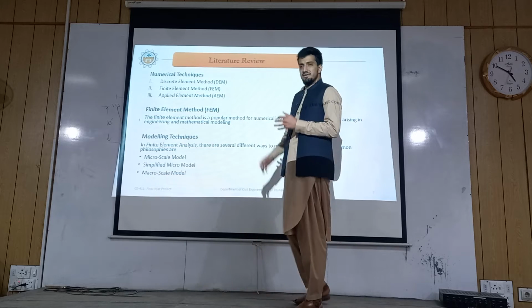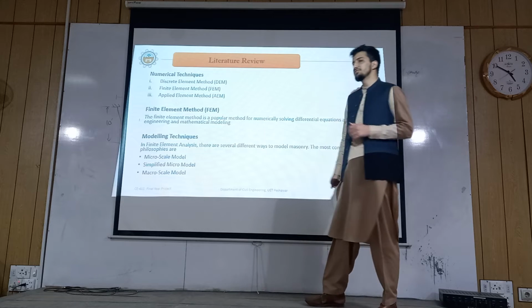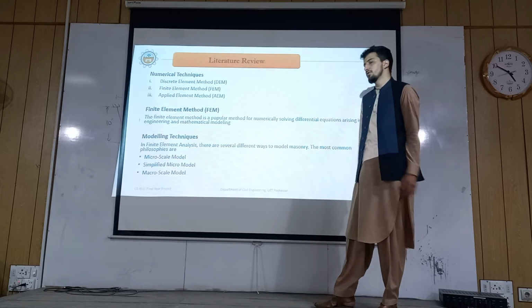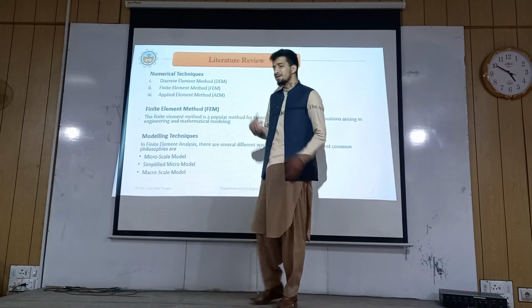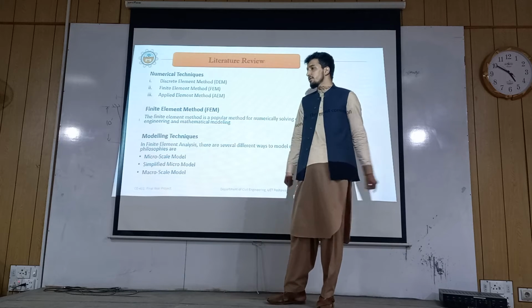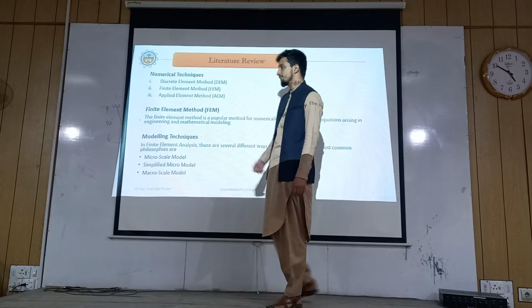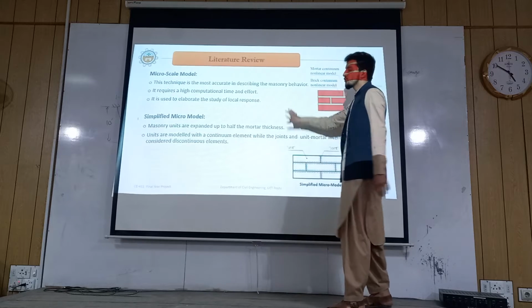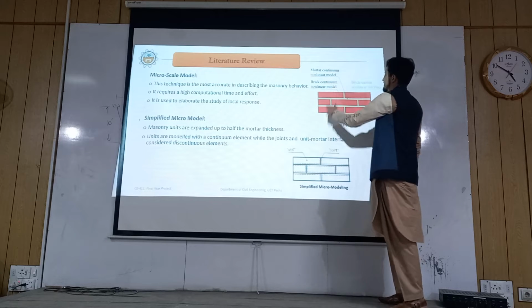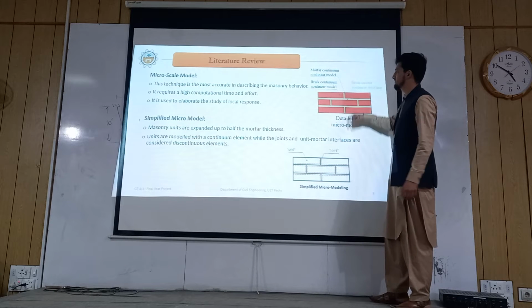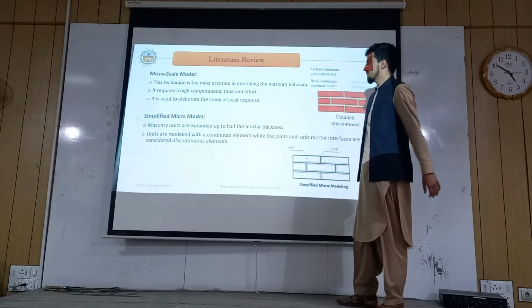The finite element method is used to solve the differential equations which arise during the solution of real world problems. After we have chosen this method, now what kind of modeling technique? The popular modeling techniques are micro scale model, simplified micro model, and macro scale model. The micro scale model is the most detailed one. In this model, we model the brick unit, the mortar, and the interface material separately, and their interaction and how they react. They are added to the software individually.